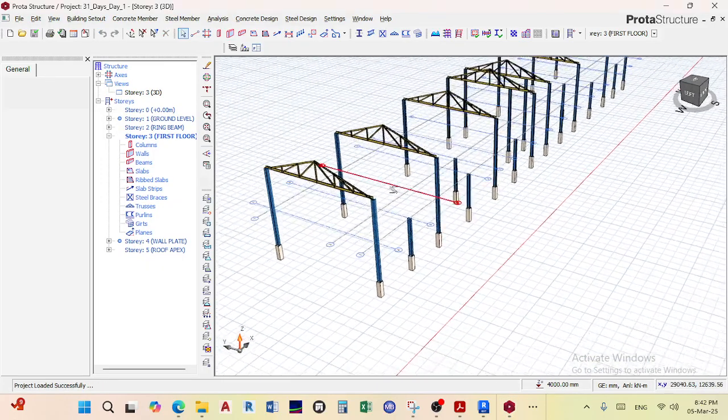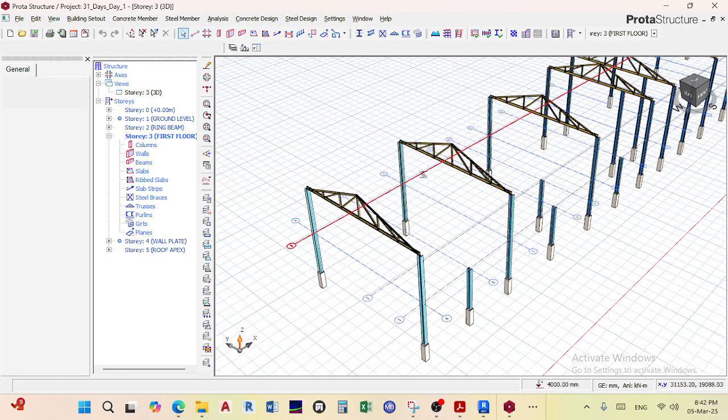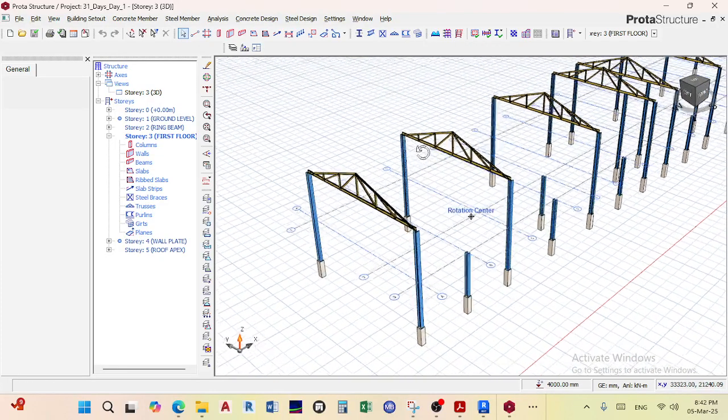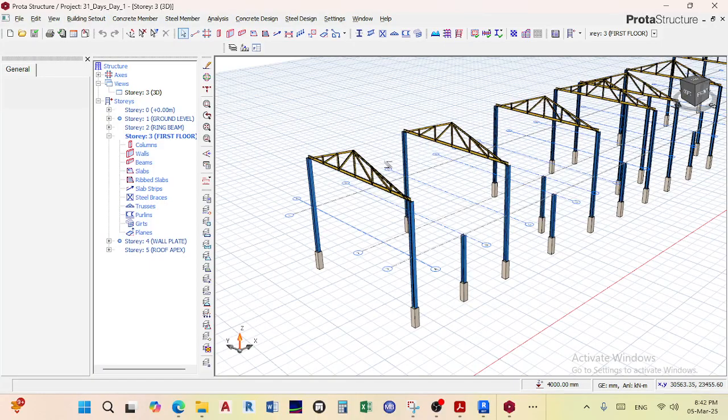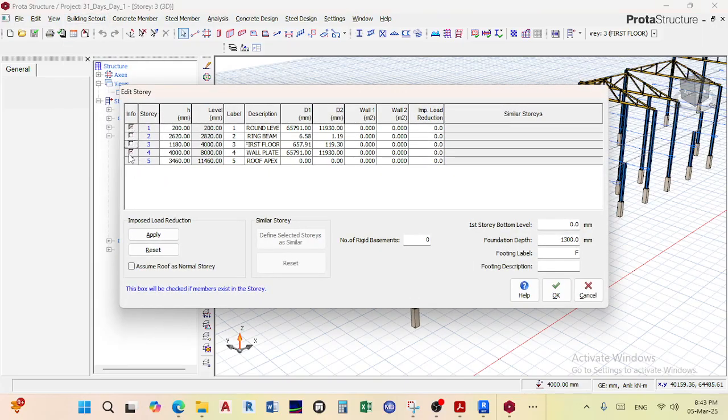So now guys, you can see from yesterday we added another floor level, right? And we also learned how we can see in the level or the floor that we have if we populated that area. Because as a disclaimer, remember I said you can only run an analysis if all the floors and the levels are populated, or they've got information in them. So when you go to Building Setout, you go to Edit Story, you've got these check boxes here for information, right?